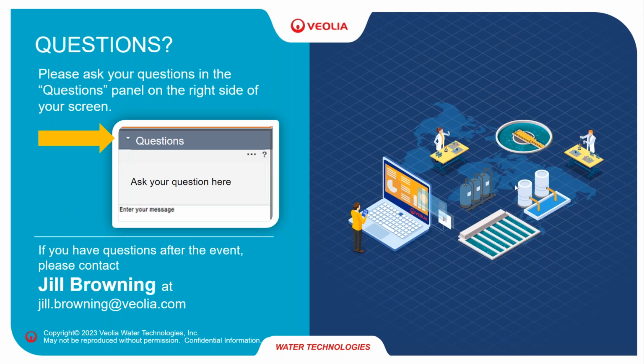Great, thanks. Another question is, what type of energy recovery device do you use? And also, is an energy recovery device even needed? Yeah, so the ones that I showed you in the presentation, we use this positive displacement isobaric energy recovery device, and the ones that we've installed so far, we've had good success using. Danfoss makes a unit called iSave where the recirculation pump is conveniently integral with the energy recovery device. And that was shown in the photograph that I showed earlier. And we've had good success with that energy recovery device.